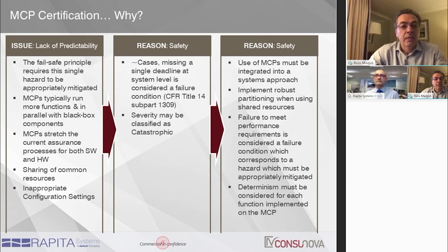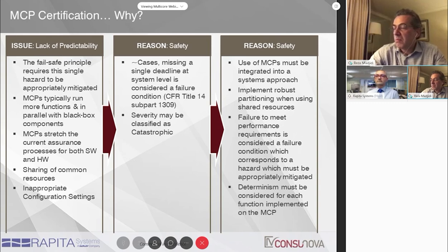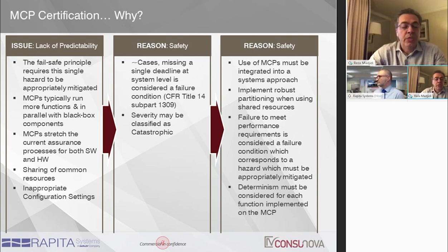In terms of compliance, we should have a software architecture and a hardware architecture in mind, so there should be a system approach. CAST-32A imposes and requires implementing robust partitioning, especially when you apply real-time operating systems to your software and your implementation. And in the end, the deterministic behavior of microprocessors is in question.